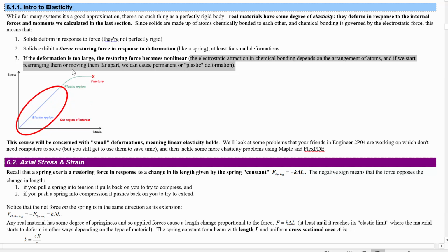Depending on the type of material, metals might have a very large strain allowed in an elastic region, and then perhaps a quite large plastic region where you can permanently deform them but they don't break, and then eventually fracture. Whereas a ceramic will have all of its behavior in the elastic region over very little strain allowed but potentially massive stress allowed, and then no plastic region at all, and just fracture. Instead of any permanent deformation, it's just going to completely shatter or break apart.